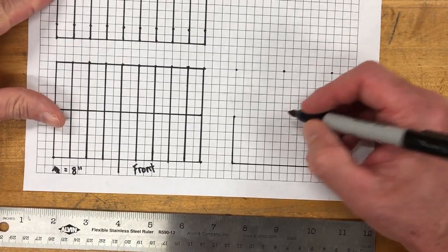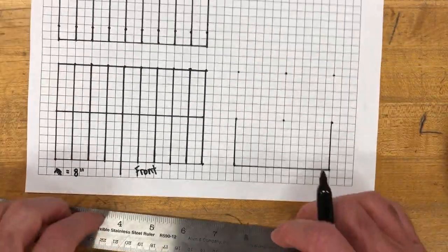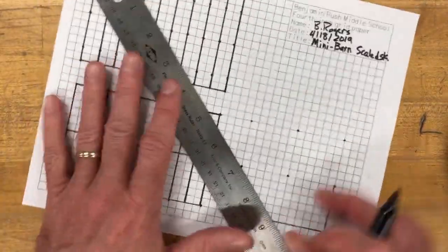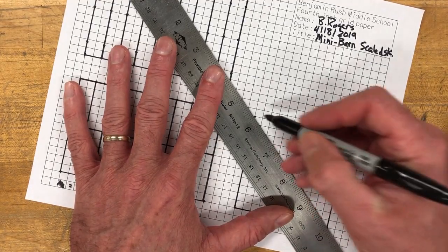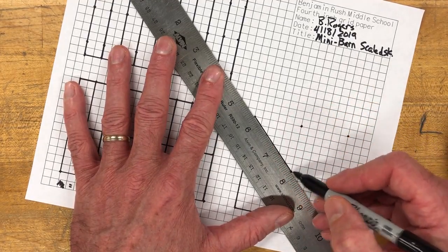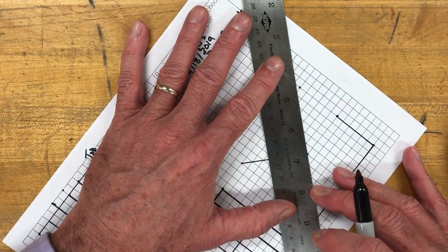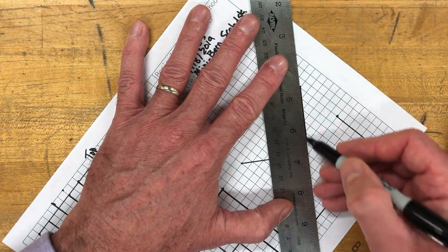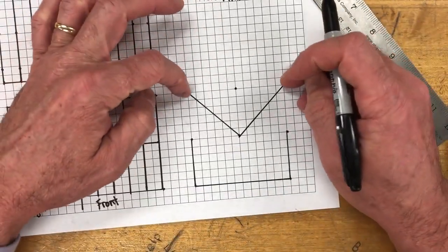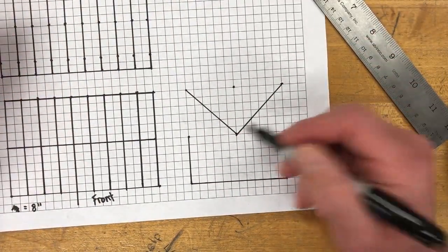Now, the roof section here is a little bit different. We're going to go ahead and start on that. I'm going to put one dot right here in the middle, right above the center point. And then I'm going to sketch some diagonal lines here with the ruler. Now these should be light lines. It's kind of hard to do with a pen, but I wanted to use a pen here to make sure that you're able to see it. What I'm doing is lining up my ruler here, putting a diagonal from the very corners of the building toward the center point, right in line with the midpoint of the wall.